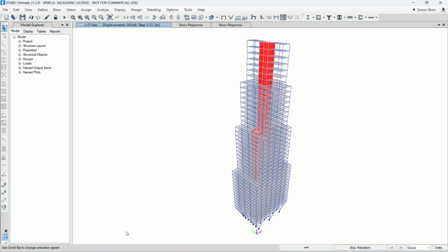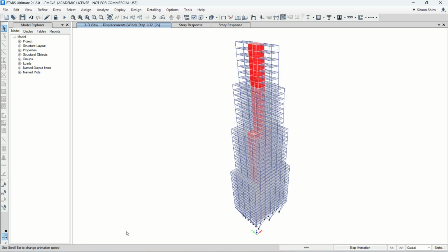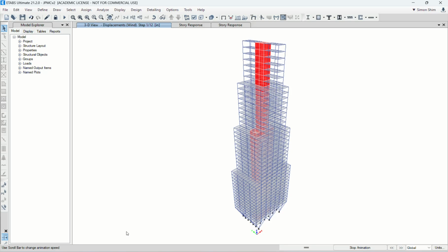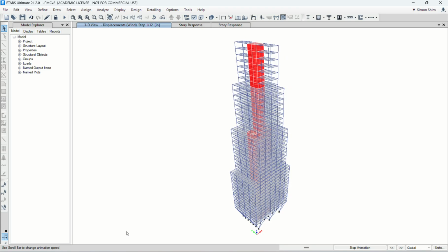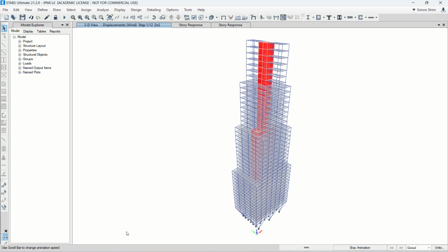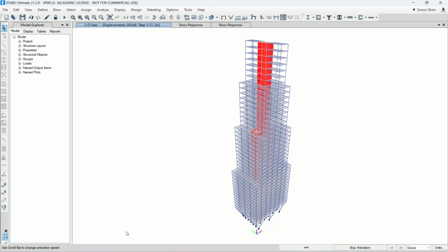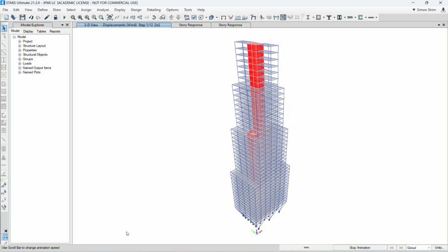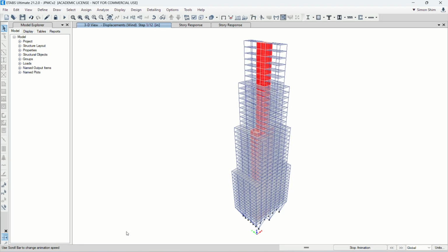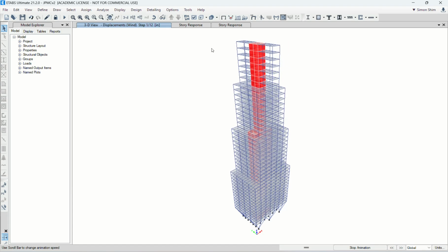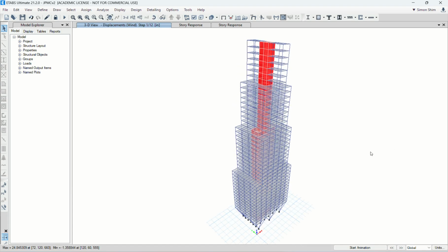You may assume that perhaps I assigned the wind load, but somehow you didn't assign the diaphragm, then it just doesn't generate the wind load. How are you going to check it? By using the reaction diagram, right? Forces continuously, you need to check, make sure you properly assign everything, and then you move on to the next, right?